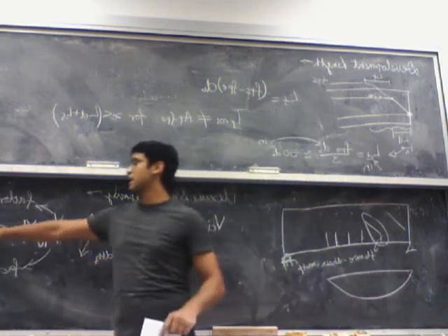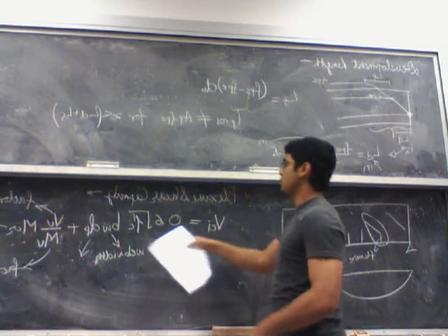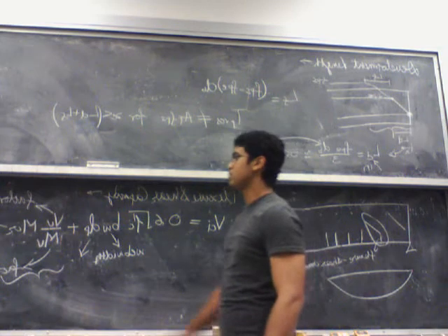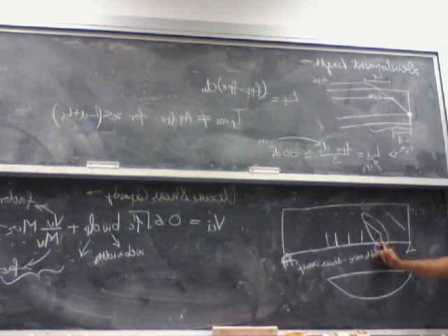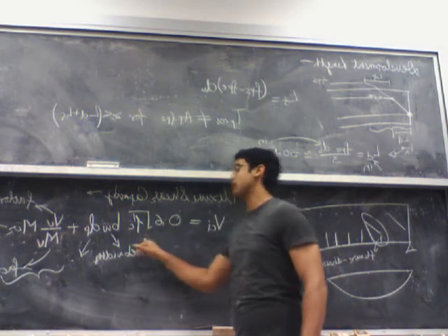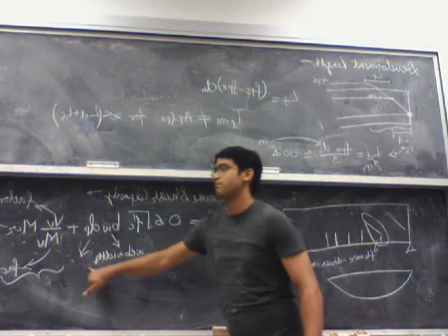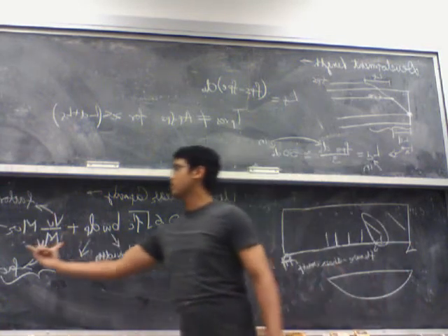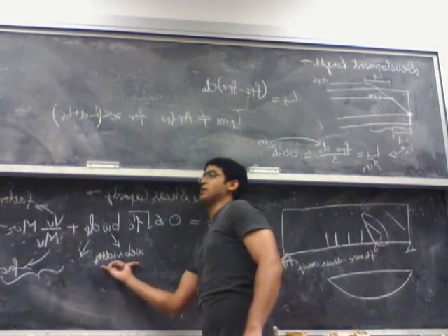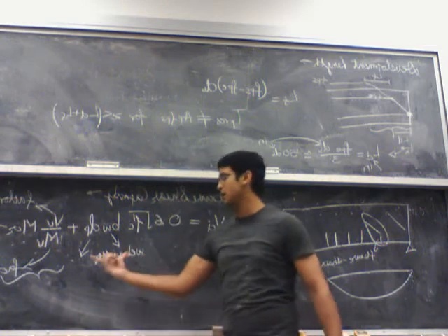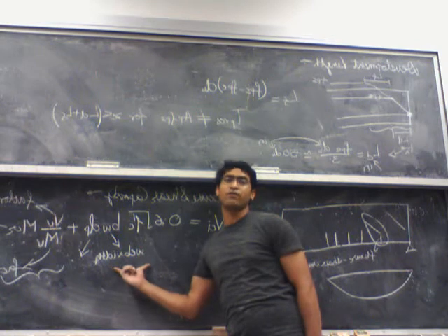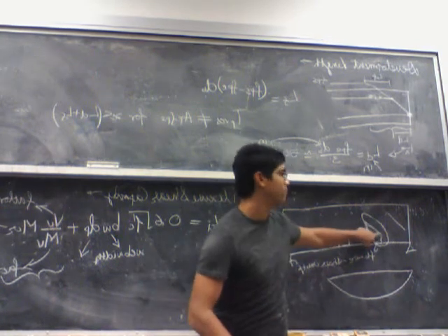And this M_cr is the cracking moment. So what this equation is accounting for is, this is the amount of shear force that you need to start the flexure cracks, plus in order to propagate that flexure crack into a shear crack, you need this extra term. So this accounts for the initial origination of the crack, which is a flexure crack, and then this accounts for the fact that if you want to propagate that crack into a shear crack, you need this extra shear force to create this part of the crack.